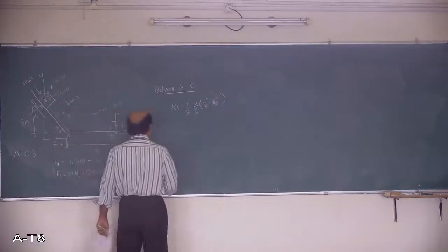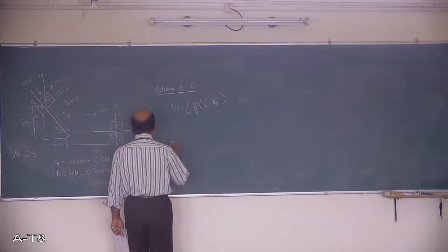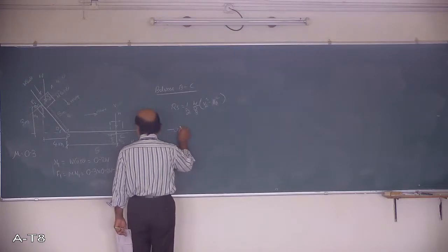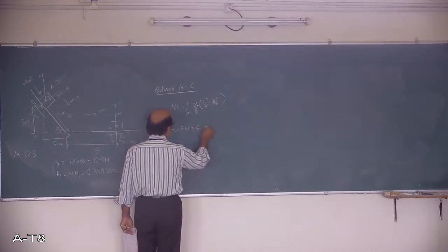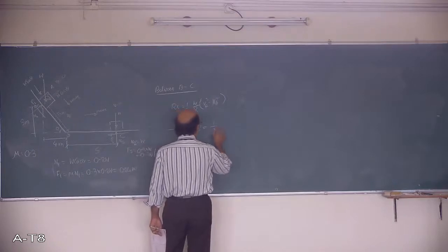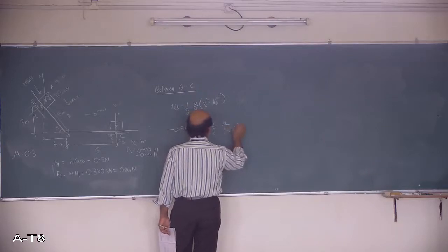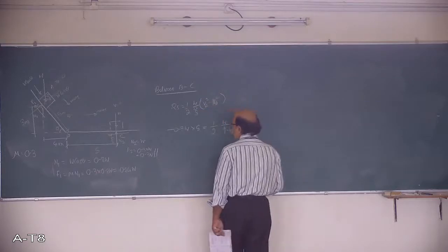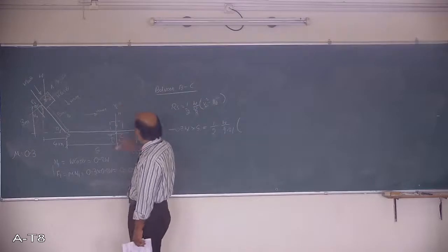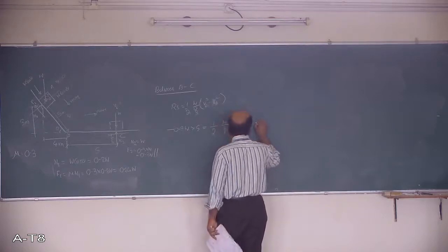So the force acting on the block is the frictional force, minus 0.3 W, into the distance S it travels, equal to 1/2 W over 9.81, times the velocity at C, which is 0, square, minus the earlier velocity I worked out, 5.943 at B square.